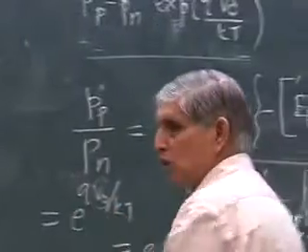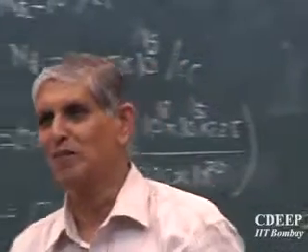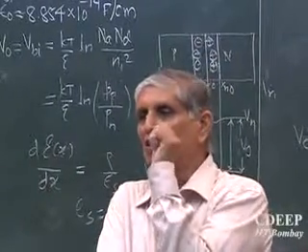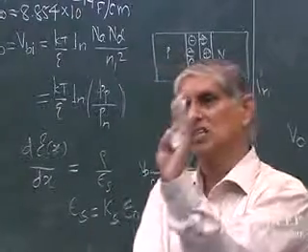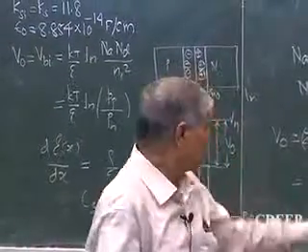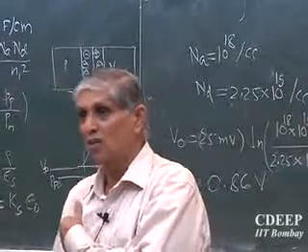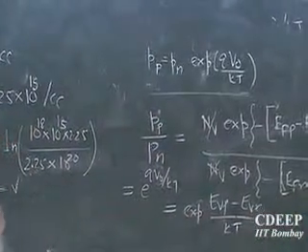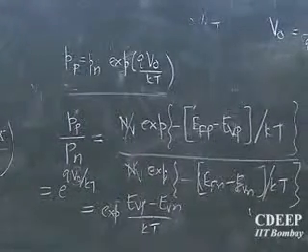Now, if I perturb this V0 by external bias, what is going to happen? If I apply some bias, this V0 term will modify, because the additional voltage may either subtract or add; we will see how. And we will see that this relationship will not hold, because it was only true for equilibrium. Why will it not hold? Because then these two values will not be equal. And if EFP and EFN are not equal, or if I apply bias, current will flow. Is that clear? Because EFN and EFP are not the same, there is dEF by dx going on, which means current will transport.